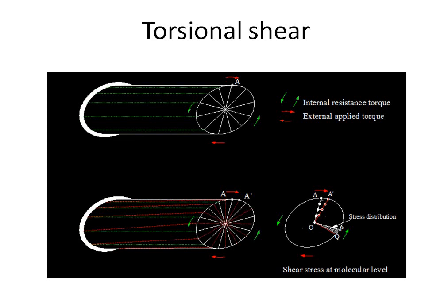Now still, we need the basics for torsional shear. So keep one thing in mind, direct shear and torsional shear are both one and the same, but in direct shear the stress is even, but in torsional shear from the neutral axis to the outer periphery the shear increases in a linear fashion. So keep this in mind.